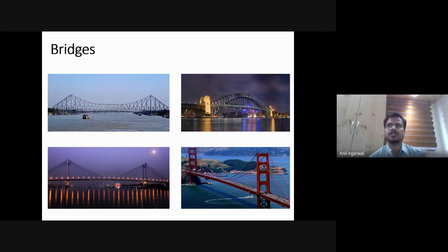Kolkata is a big center of the steel industry in India, and you can see a lot of big steel structures and steel bridges still present from very old times, and many big industries which use a lot of steel are also based in Kolkata. So this is Vidyasagar Setu, which is also primarily steel. Cable stayed bridges can be of both kinds. The deck, the slab, in all these bridges will of course be concrete, but the beams are all steel, and of course the cables are steel.